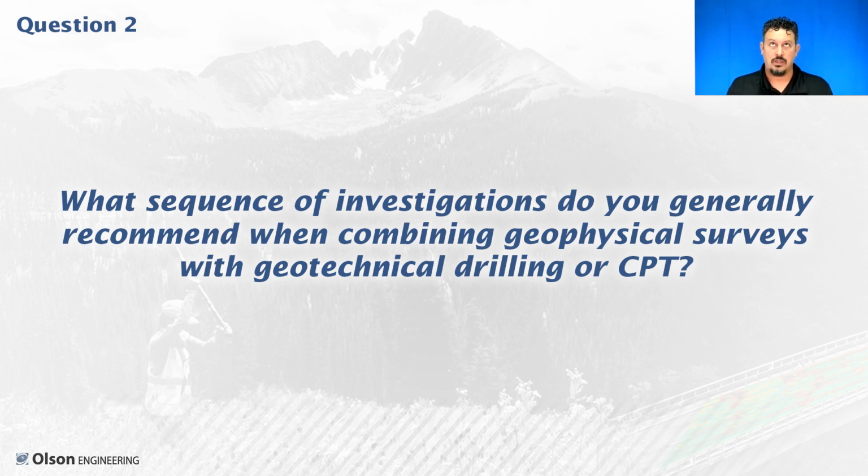And then we looked at doing additional resistivity surveys at different depths of the CPT push. What we eventually concluded was that we didn't need to do additional depths, that the maximum depth that we went to for the CPT push gave us another current electrode at depth, so that could improve the subsurface resolution.